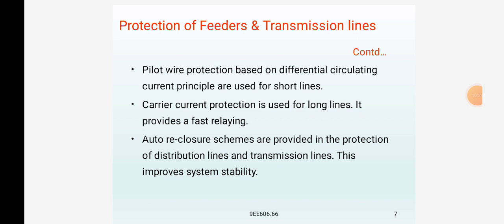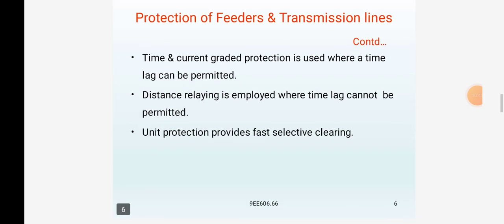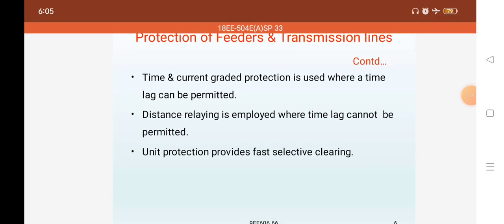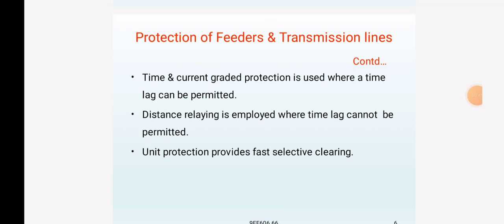The switchgear frame is lightly insulated from its adjacent earthed structures for this scheme of protection. In case of a station having an incoming transformer and two outgoing feeders, as will be seen from this figure, the switchgear framework is connected to the station main earth through the primary of a CT.